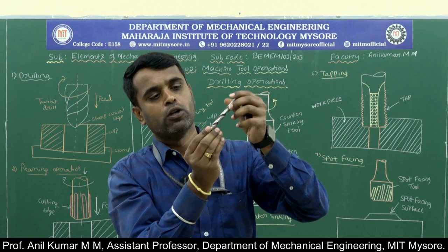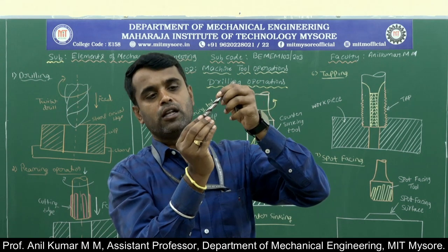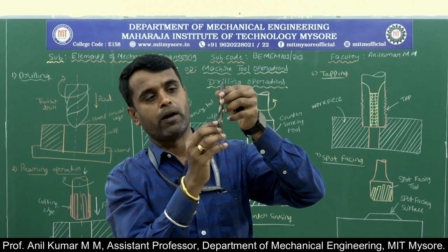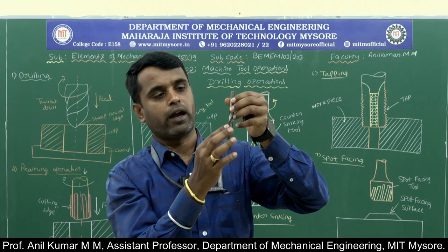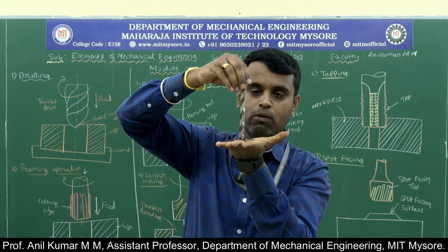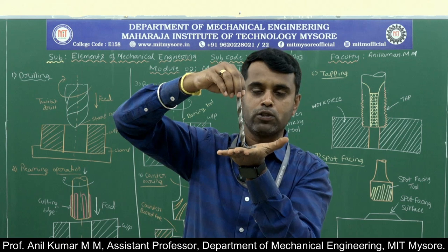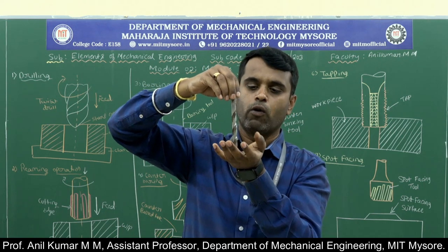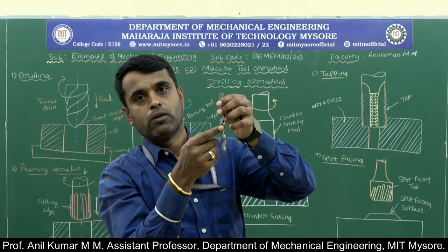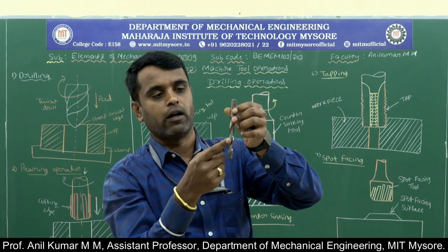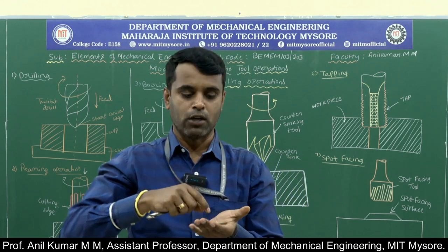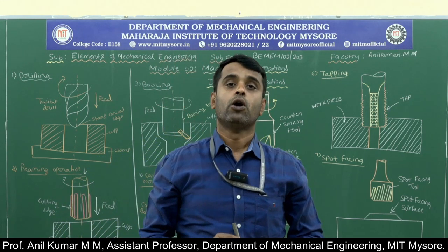The drill bit has sharp cutting edges. Here the sharp cutting edges are provided at the bottom and the twisted edges are provided at the periphery of the tool. Also, helical grooves are provided on the tool. When the sharp cutting edges touch the workpiece material, they remove the material from the workpiece surfaces. Whatever metal is removed will be curled and will escape through the helical grooves provided on the periphery of the cutting tool. Hence the machining takes place, and the cylindrical shaped hole is formed on the workpiece material.